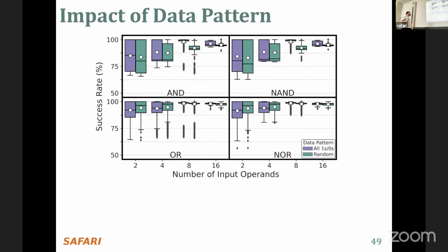So this memory array should be fast, right? It should serve very fast. To have that fast speed, they need to have hierarchical row decoder circuitry. You can think of it as a tree, and when you try to activate one row, you assert multiple signals in that tree.